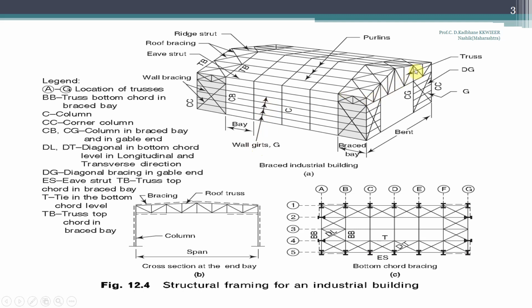Here this is a roof truss. Then here there is an opening provided to the industrial structure, where these are the bracings, you can say cross bracings, and these are longitudinal bracings. Whatever bracing is provided at the top is called top bracing, whereas these are called longitudinal bracings. Here this is a vertical column and a roof truss.